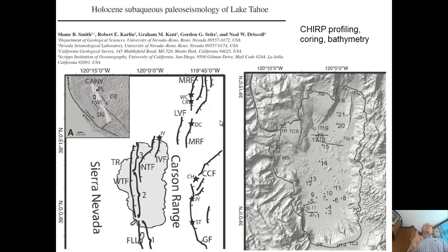One of the problems with seismics on land is the coupling, the signal coupling to the ground, we call it. The second one is the topography. The statics are very hard. So it's much easier to do seismics in water. And so we see the biggest application in marine seismic profiling, but also lacustrine, so in lakes.